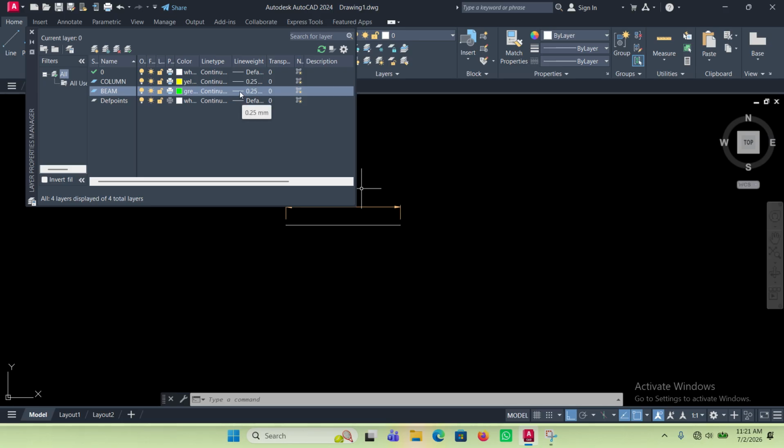These layers we can turn on and off when we are working on the structure. This is where you turn it off. Once you lock this padlock, you have turned it off. Whatever entity is on it, you cannot select it or work with it. Once you click it again, you open the padlock and you can select it and work with it.